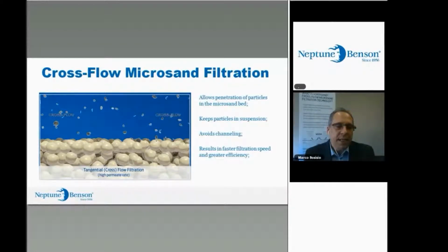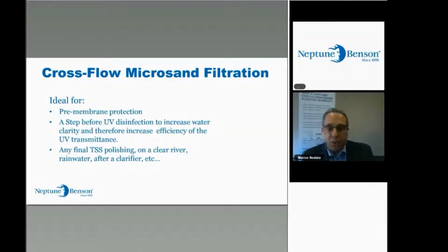So the idea again is to keep the particles in suspension, avoid channeling, and allow penetration of particles within the microsand bed, which is, by the way, only 8 inches. So the system is very shallow.